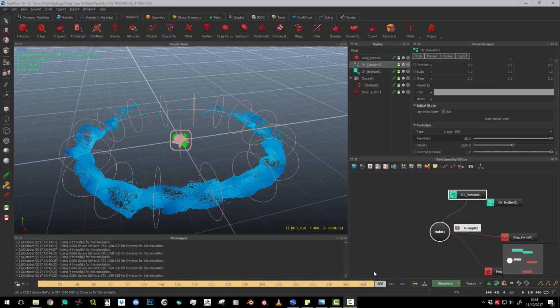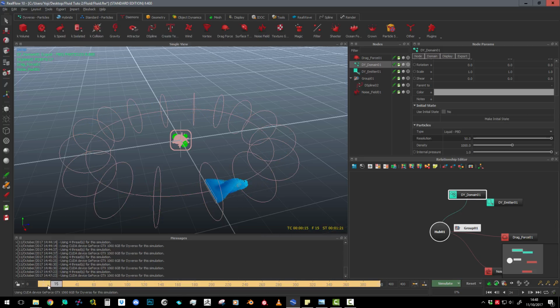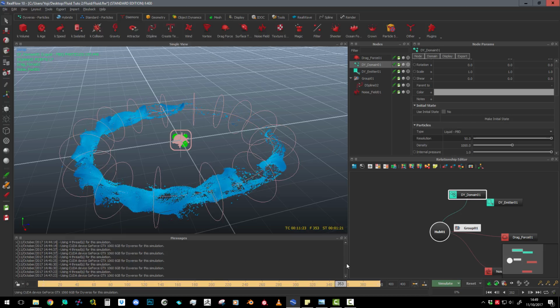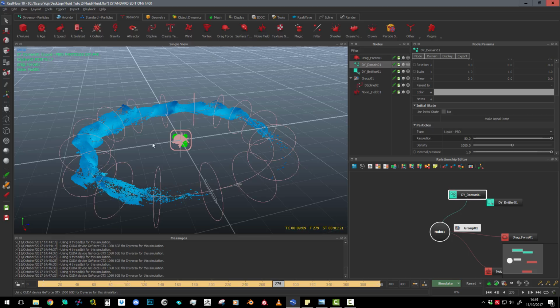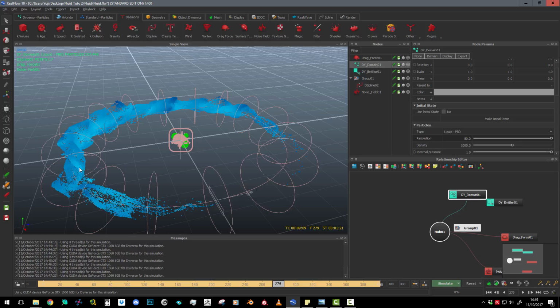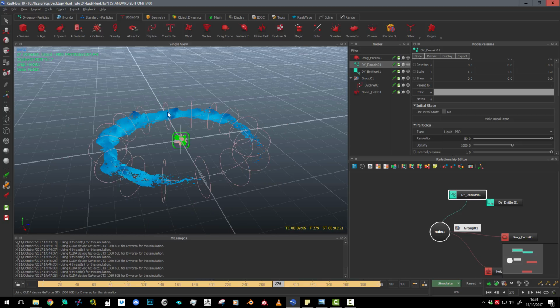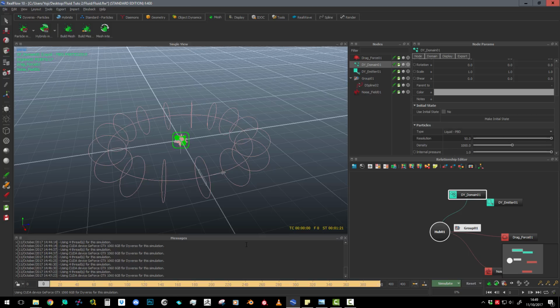Okay, good. We did our simulation, so now you can play with the frames here and look how beautiful the simulation is. It will be very good if we have this in Blender, huh? But for now we will have to create a mesh, because what we will import into our Blender file will be an Alembic mesh, and for that we have a meshing system that goes around the particles and makes a mesh around the particles to build drops and liquid around it. So what we use for that is this mesh section here, and you can just create a particle mesh.